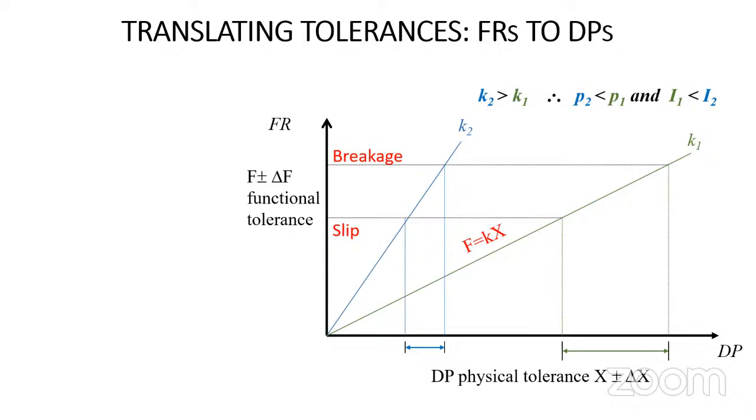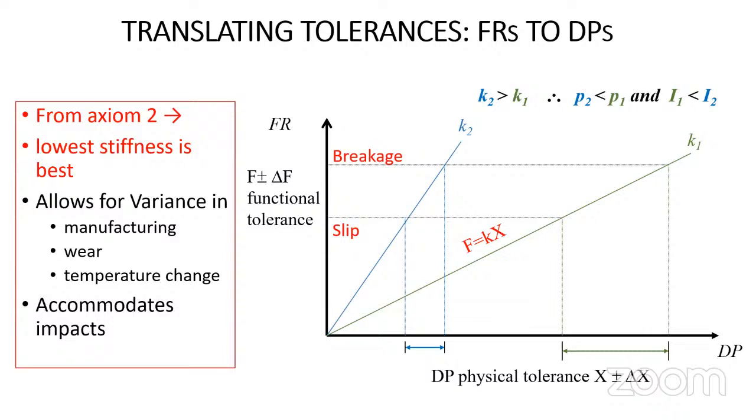So whenever we have a linear system like this, and be able to choose, or the design problem, faced with you're doing your MQB and you're thinking, well, let's see, which component should I put in here? Which one's going to work best? Figuring that. So longest is the best, variance accommodates impact. Also, though, the soft spring takes up more room and more displacement. So maybe there's a constraint on how big it can be. So within the constraint, maybe I take the softest spring.